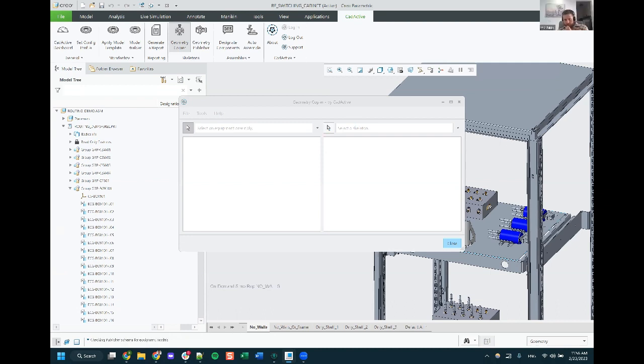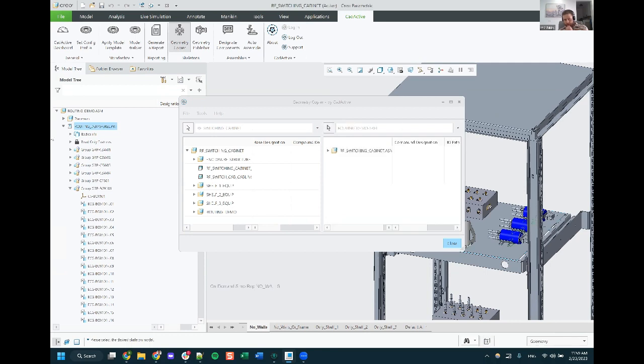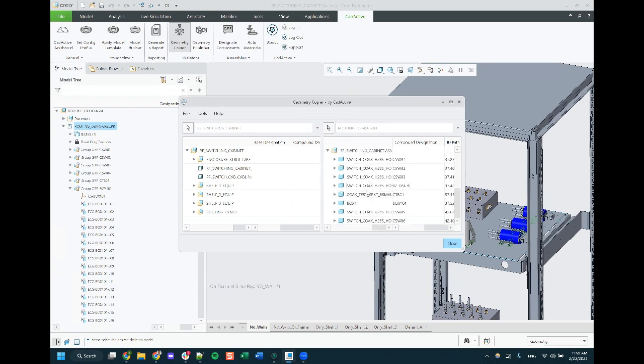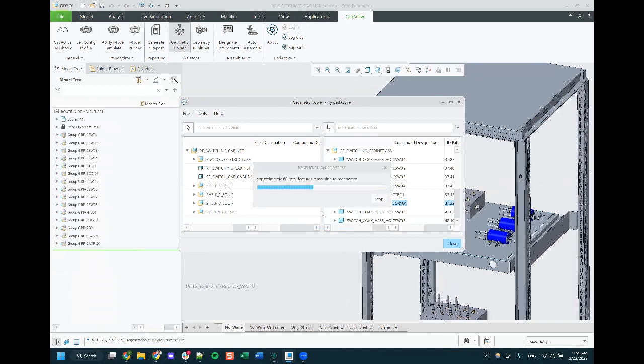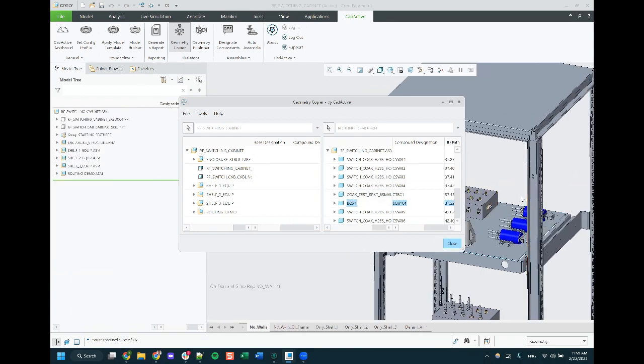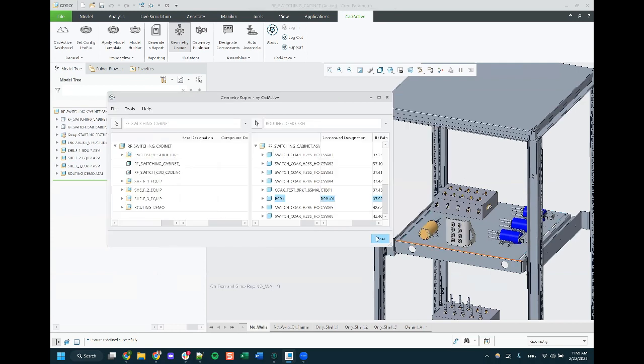Rebecca posted a question: what does removing the skeleton from this assembly do to the copy geometries in a skeleton? If we remove this skeleton, which contains all of these external copy geometries right now, we are deleting all of the copy geometries as well. So they would all be gone. And because we are assembling all of our connectors to those copy geometries, now we would have problems, right? That's not going to be a good thing if we delete that skeleton model, but it's no different than the way that you would normally work with Creo.